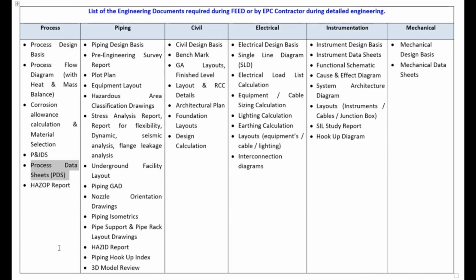Then it's coming to the HAZOP report, as we know. We have all discussed HAZOP in the past also. But the HAZOP concept is that when you are doing HAZOP, you are looking for any hazards in operations, correct? The basic assumption is that all the designs and these documents are frozen. That means the engineers have done their job very well. The design is completed, P&IDs are approved, process data sheets are approved, everything is done. And then you are conducting a HAZOP for that.